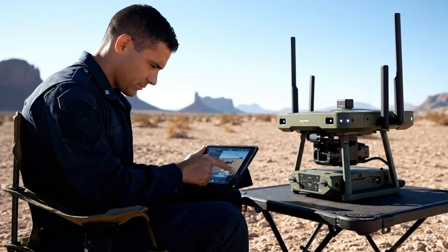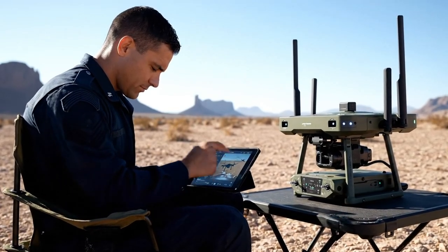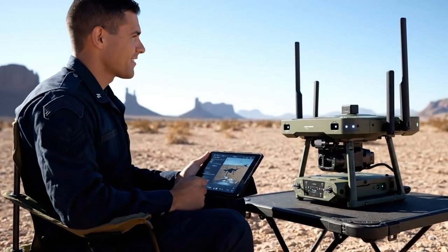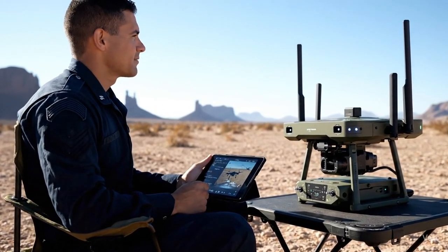This is a method that is very commonly used these days, and you can definitely use it to correct the position of the drone and make it closer to the real position, so that when you process your data, you've already got the right GPS values in there and you're able to get much more refined and much more absolutely accurate results when it comes to drone mapping. So that's basically the RTK side of things.